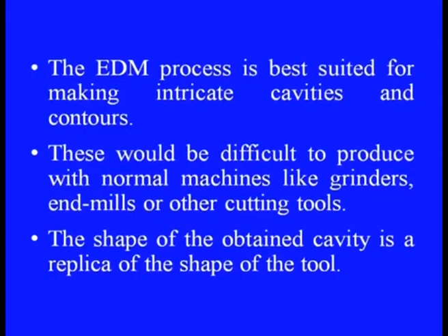But the only limitation of this process, major limitation I must say, is that only electrically conducting or semiconducting materials can be machined by this process. The EDM process is thus best suited for making intricate cavities and contours. This would be difficult to produce with normal machines like grinders, end mills and other cutting tools. The shape of the obtained cavity is a replica of the shape of the tool.